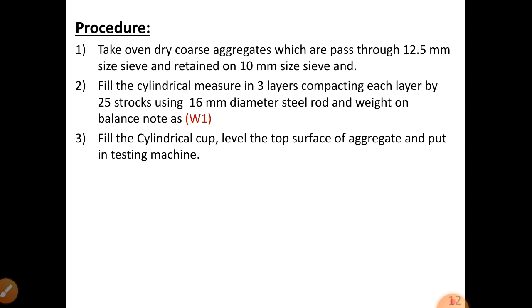Fill the cylindrical cup, level the top surface of aggregate and put it in the testing machine. Apply 15 blows of a 14 kg hammer from 38 cm height.